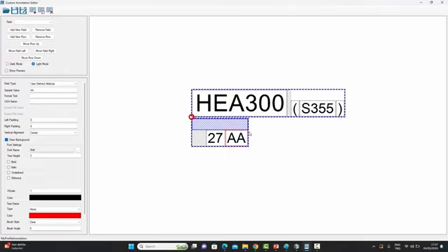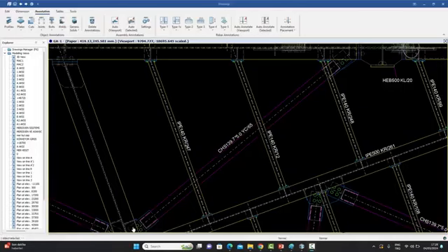You can save them away. And when you save them away, they will appear in the annotations command. That's how you will use them. So the first thing you do is you create these annotations, save them in this file. You can be happy with how they look. You can change the font size and this and that. And once you're happy and they're exactly the way you want them to be, then you save them in the file, and then you go ahead and you use them the way you use your normal annotations. And I'll just show you how you do that.